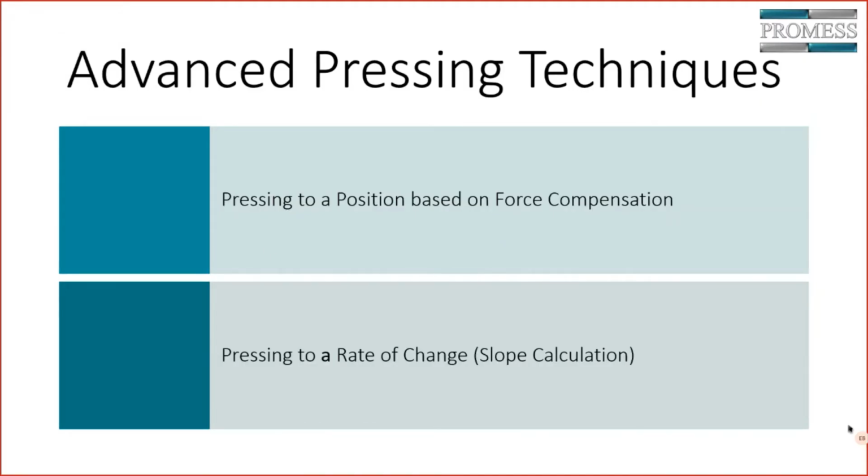Advanced pressing techniques utilize both force and position when making decisions on where to stop. A few of the advanced techniques are pressing to a position based on force compensation and pressing to a rate of change.